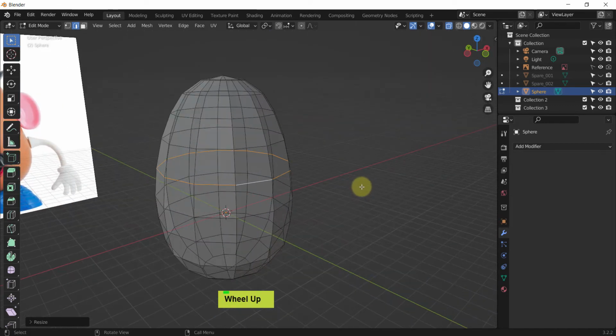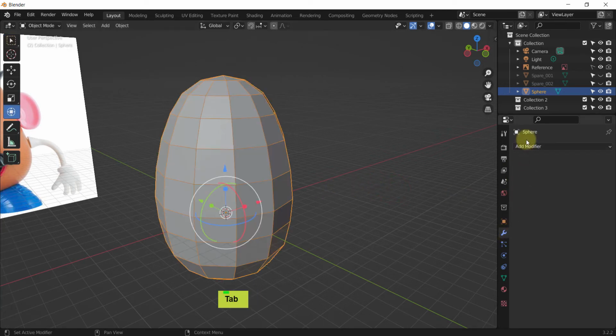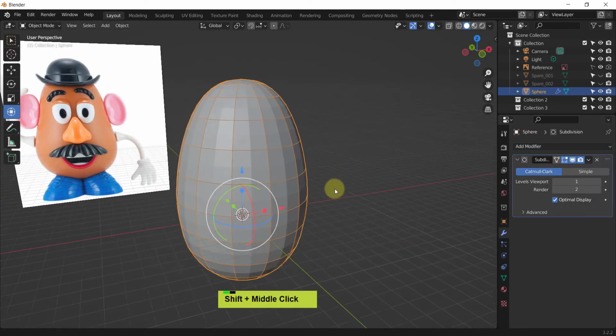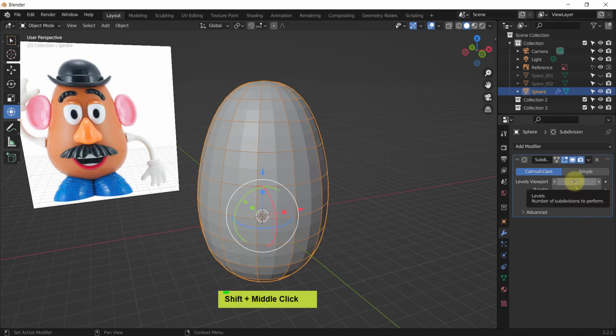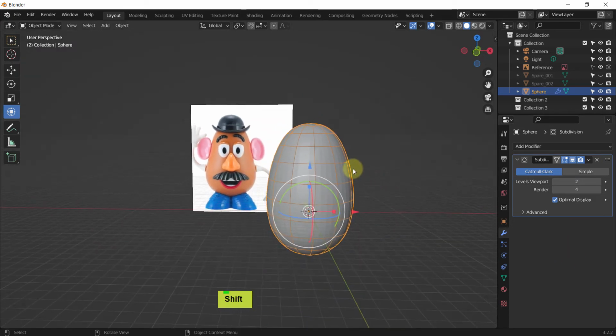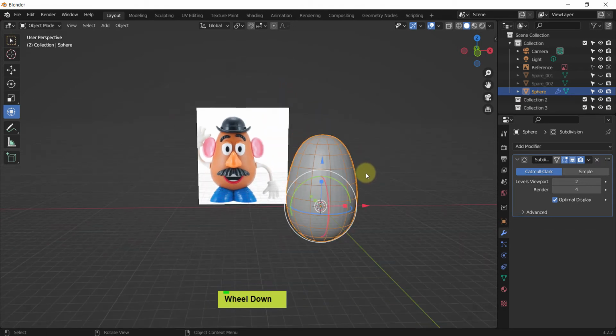So right away, let me turn off the see-through mode, and go to object mode, and apply a subdivision surface modifier, with levels in the viewport. That should be at least 2. Yeah, so it's not that blocky, and because 2 is already not enough in the rendering viewport, we should crank it up to about 4, so that will generate a nice rendering smoothness.